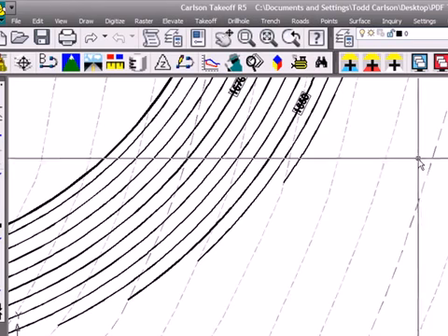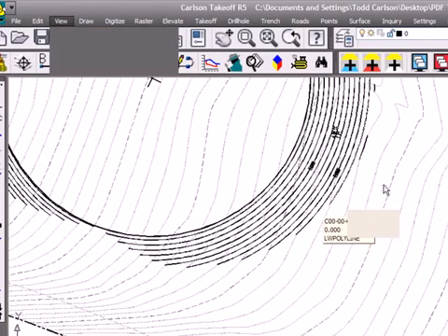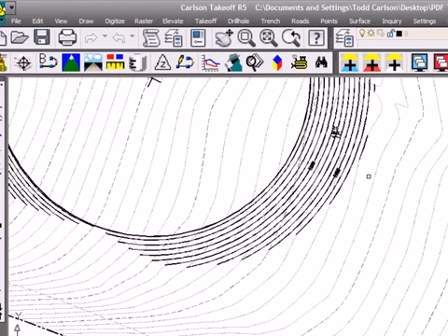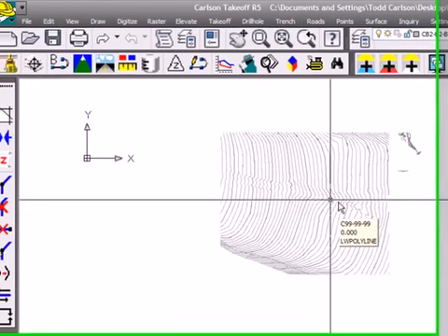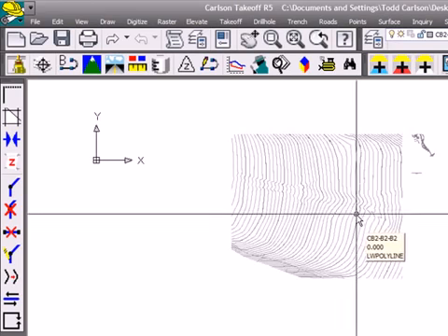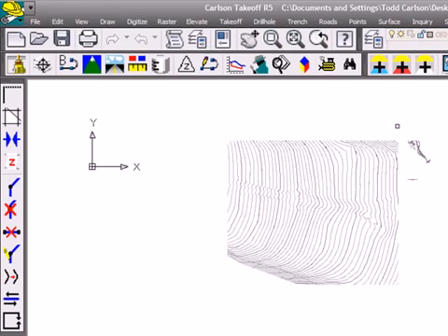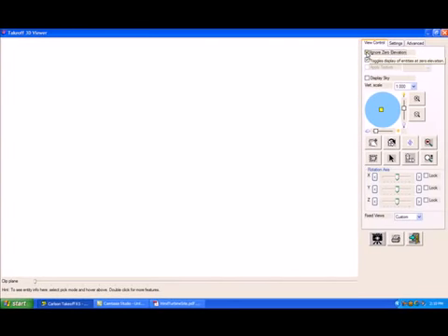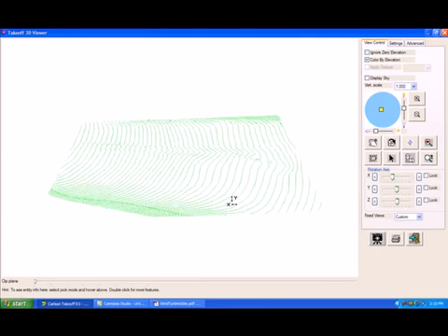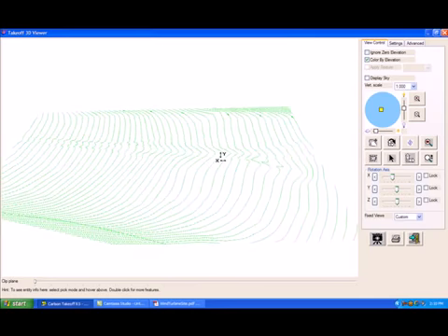So let's look at just these existing contours. If I look at just these two layers, the major and minor are two different colors, and I were to look at this in 3D, I'm going to uncheck ignore zero elevations, and looking at this in 3D I can see everything's at 0 elevation.